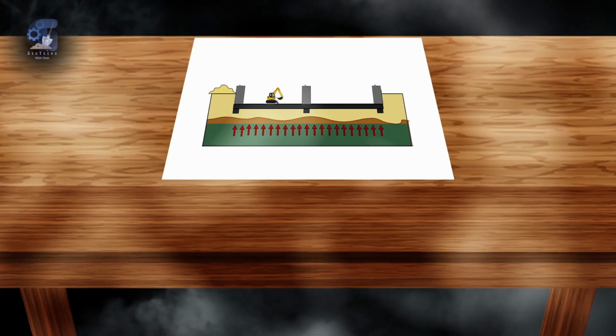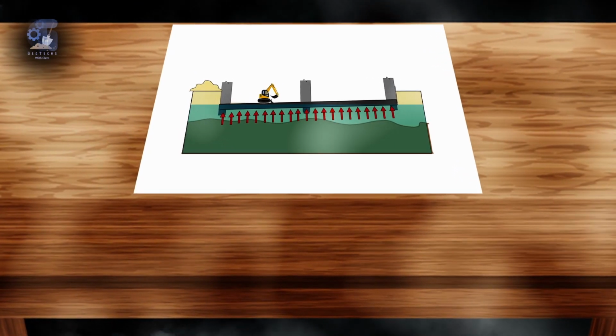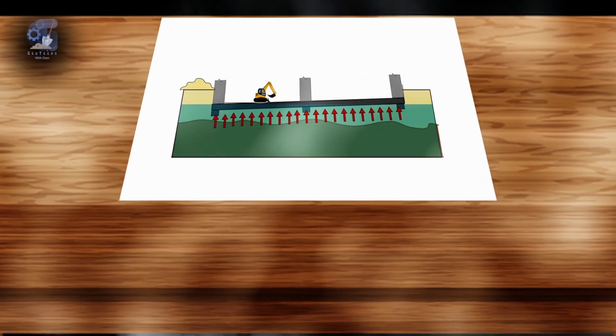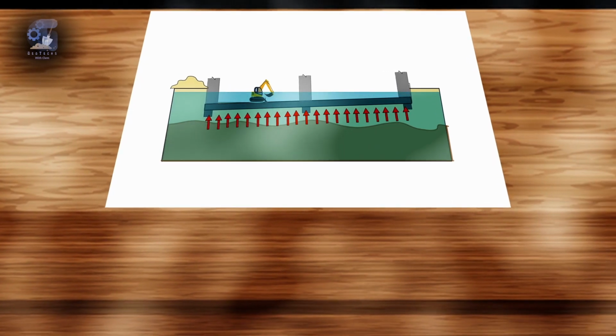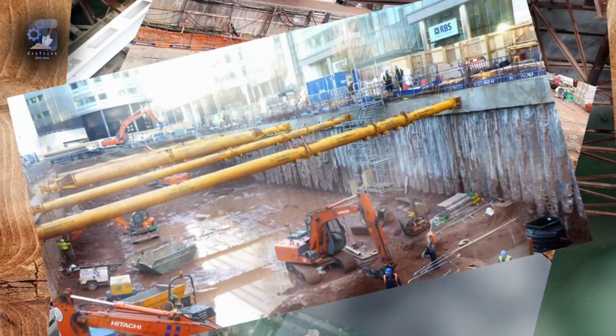Lack of groundwater information may lead to under-design of uplift pressure, especially for raft foundations. Moreover, unexpected and uncontrolled groundwater ingress may lead to construction site flooding, loss of equipment, and even loss of life. So, groundwater information is essential for designing the groundwater control scheme or dewatering program in the event that the project requires excavations below the water table to create a conducive work environment.